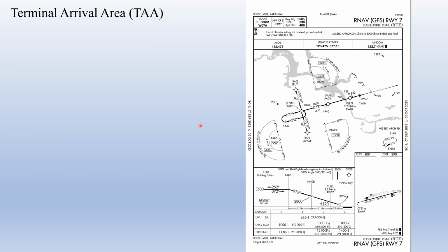So how this would work, let's assume that we are approaching from this direction, from roughly the west southwest, and we are cruising at an IFR altitude of 5,000 feet for our eastbound flight. And we are within 28 nautical miles. We've been cleared direct to PAB, and we are 28 nautical miles from PAB. So approach or center calls up and says, you are cleared for the RNAV GPS to runway 7.